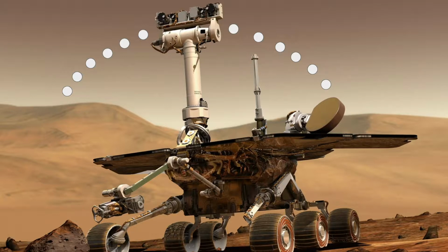There's other things that go into play, such as the surrounding terrain. So if there's a mountain blocking your view, you can't send data during that period of the overpass of the satellite. The rover has a lot of instruments on it, and these instruments can also affect the path between the antenna and the satellite, which will cause it to not be able to send as much data.